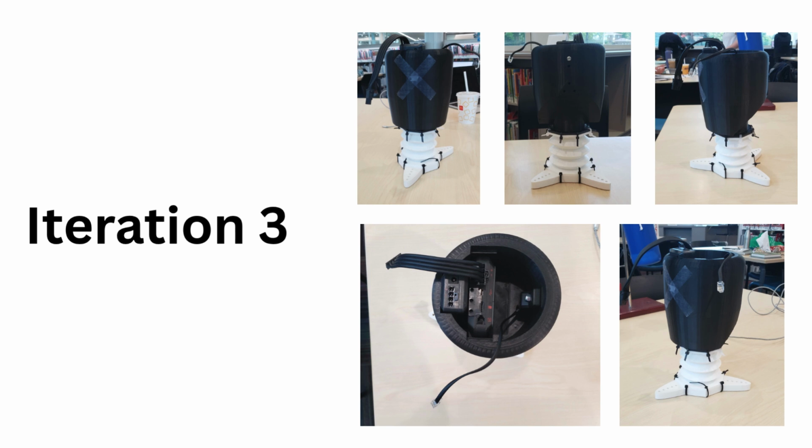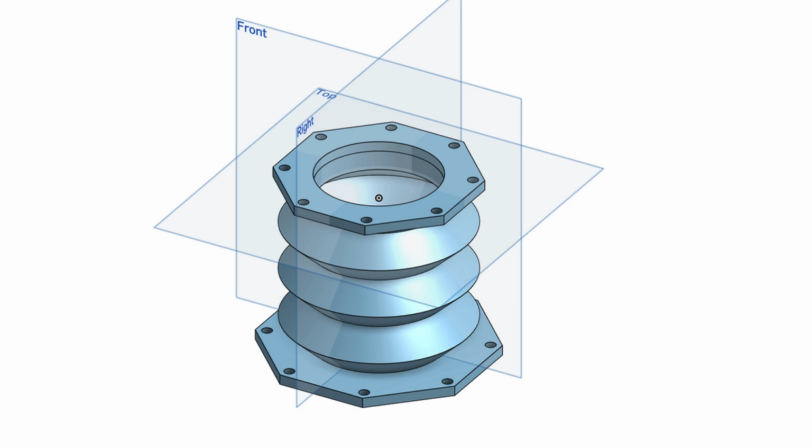So in iteration 3, the biggest thing that we noticed was the head tipping over completely and not having a neck that properly mimics the mechanics of a neck and head system. So the PETG neck was too hard and did not allow the neck to bend. So we produced a TPU neck. We chose to make the neck very long and used a bellows design, as it allowed for high lateral strength while allowing the neck to sway.